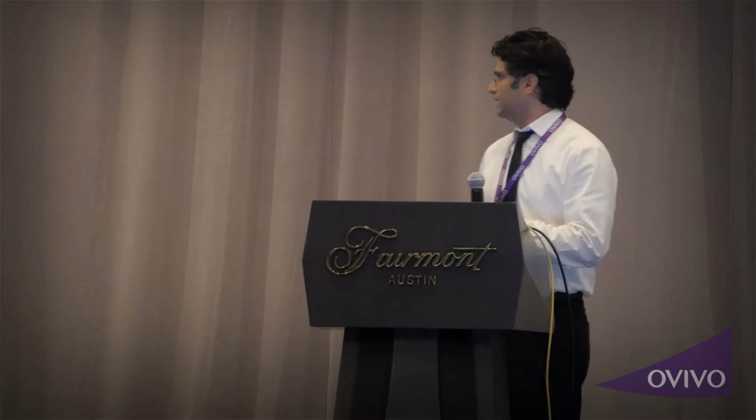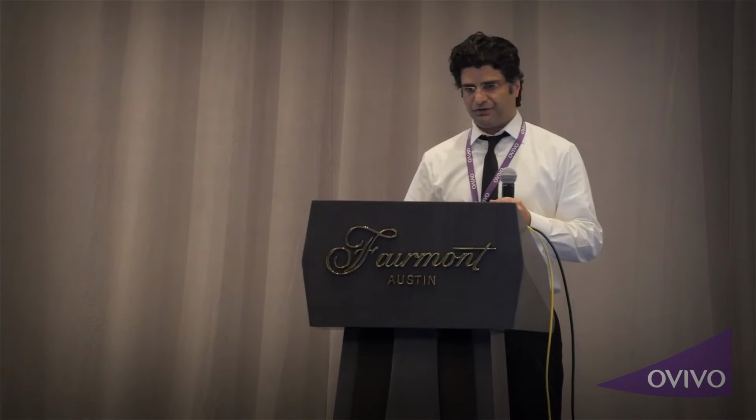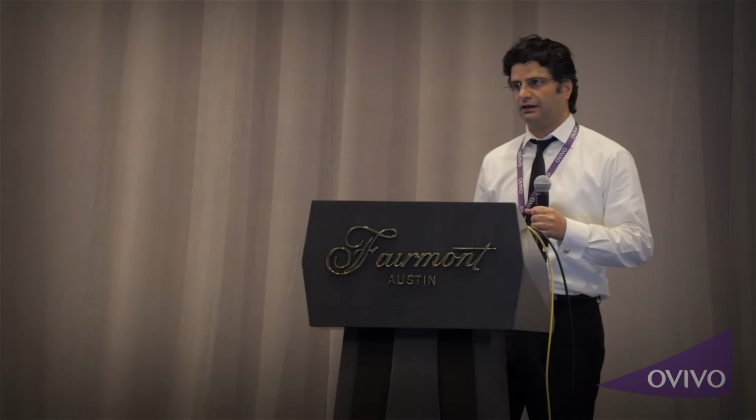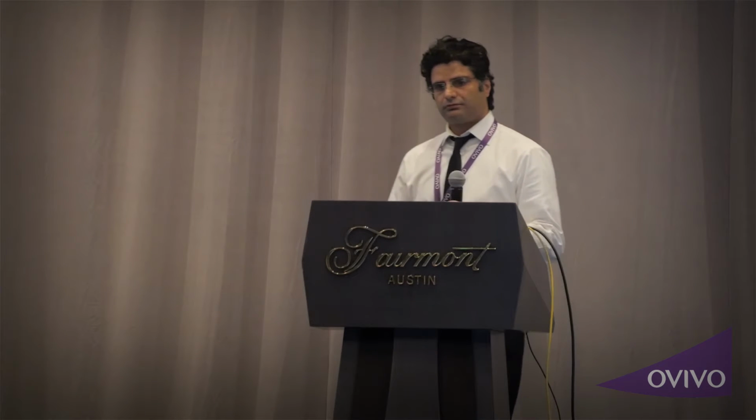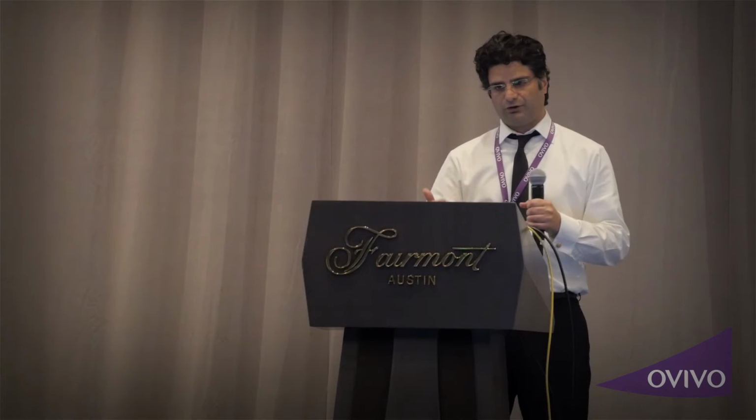Another challenge was proper mixing in other basins, such as the anoxic basin, or short-circuiting, another sort of mixing issue. If you have short-circuiting, we have a dead spot in the basin, which is causing septic condition, and short-circuiting in another section of the basin, which basically means we have a shorter retention time than we designed for. So we try to avoid all those.